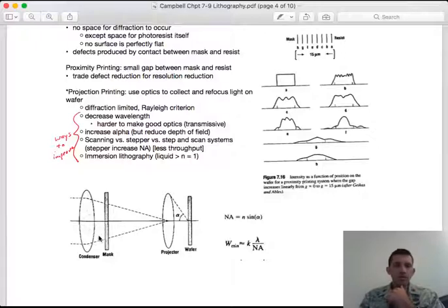And you took the mask and focused it onto that 1/4. Optically, that would allow you to have a mask that is 4 times the size of the wafer, which makes it easier to make your mask in the first place before you then use it to expose the surface of the wafer and create your pattern.